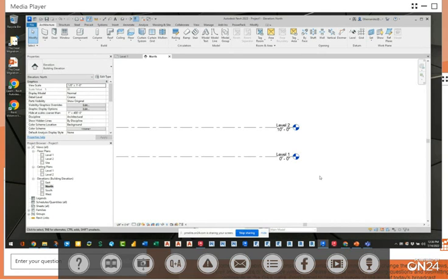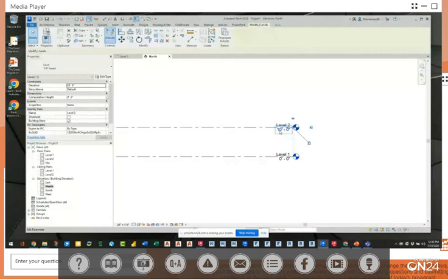So you guys set your levels. Is this 100 feet or is this at 0 feet, 0 inches? Is your level 2 at 19 foot or 19 foot 6? Top of steel, finished floor, what are you measuring to, right? So that's why it's critical to have your plan and to figure out this part first, set it up, and then once you start the modeling process, everything can kind of come together, okay? We'll get to that here in a second.